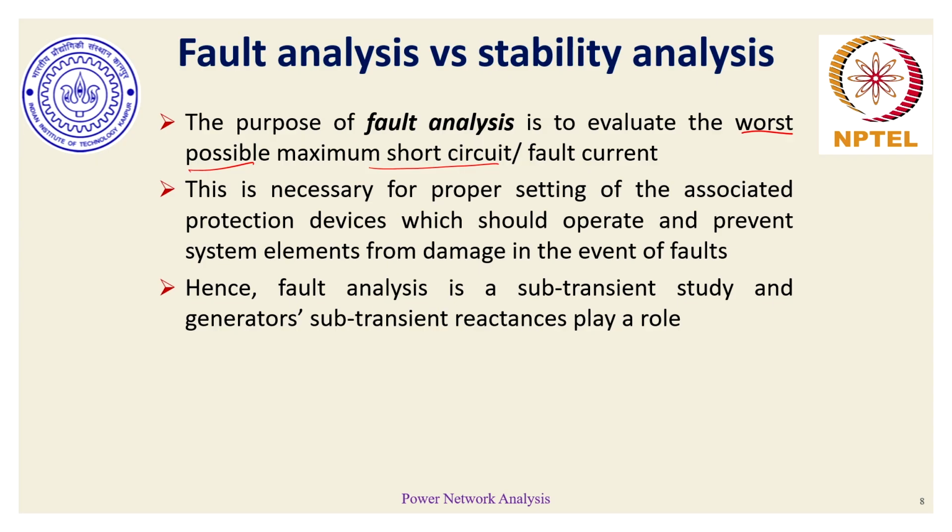Power flow analysis is a steady state study, so we don't go inside the machine. In power flow analysis, we refrain from going inside the machine. We restrict ourselves only to the terminals of the synchronous generator. In the context of power flow for synchronous generators, we have been considering PV buses and slack buses. We went into the logic of conversion of a PV to a PQ bus when the voltage control or reactive power control of the synchronous generator is lost.